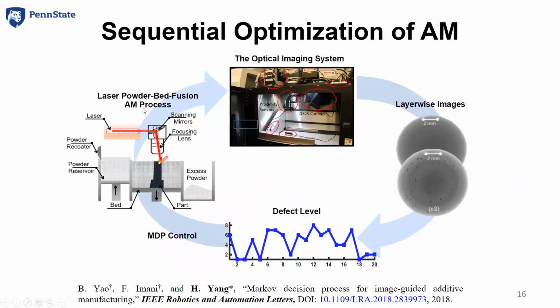Because there are large process variations, we can do the LPBF in laboratory settings, but when it comes to real-world manufacturing settings, it's not good for mass production because the yield is too low, the throughput is too low. Of 7 parts, only 3 of them are defect-free. So the cost is high.